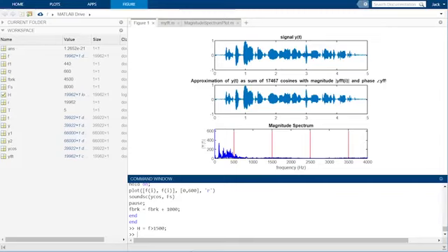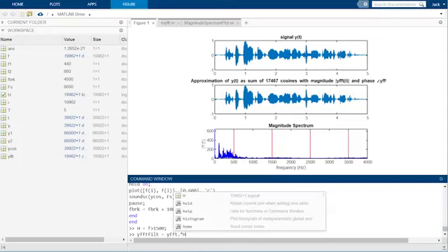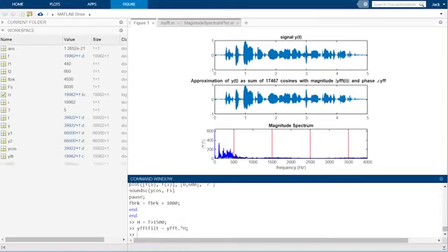To apply the filter, we simply do an element-wise multiplication of the FFT of the signal with the filter. This gives us the Fourier transform of the filtered result, where the amplitudes of the cosines we would use to reconstruct the function that have frequencies less than 1500 Hz have been zeroed out.